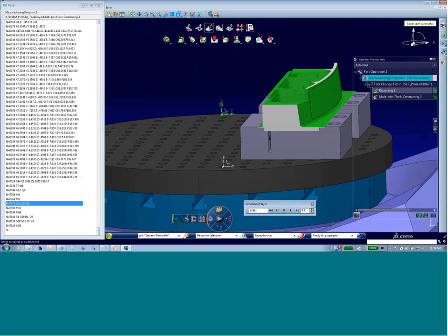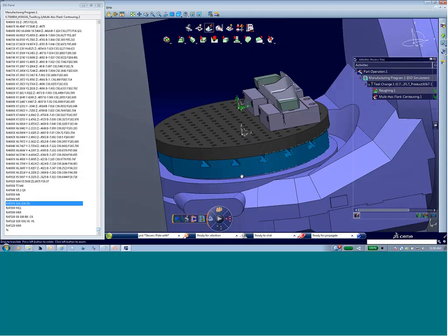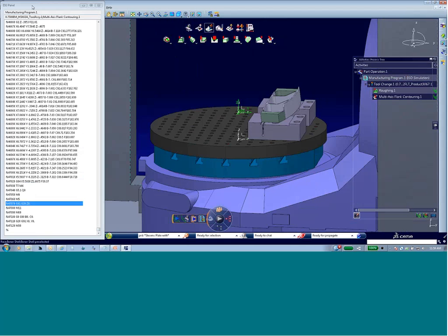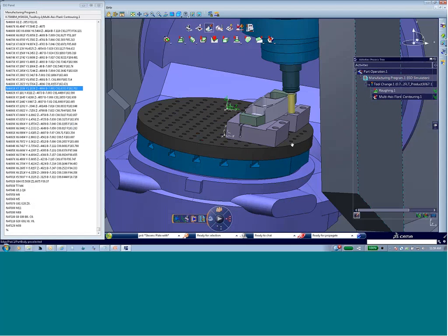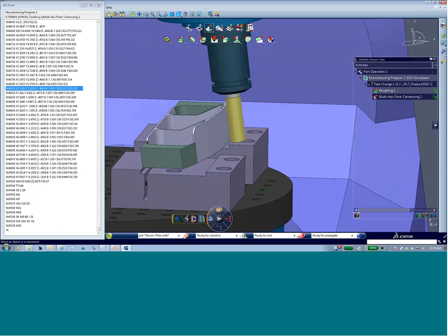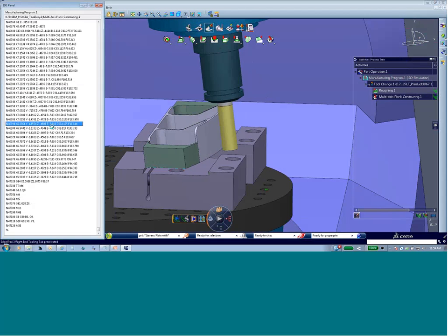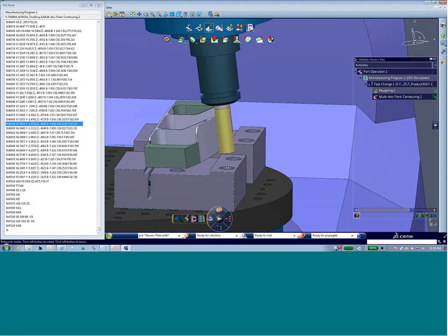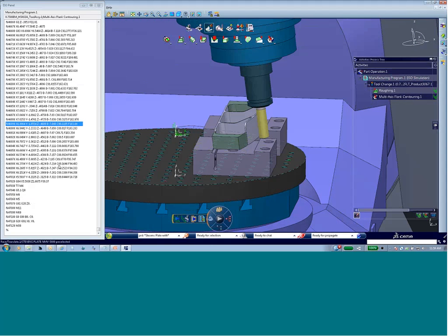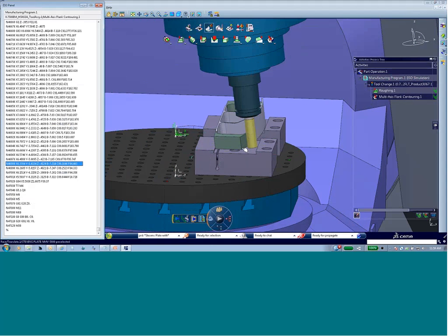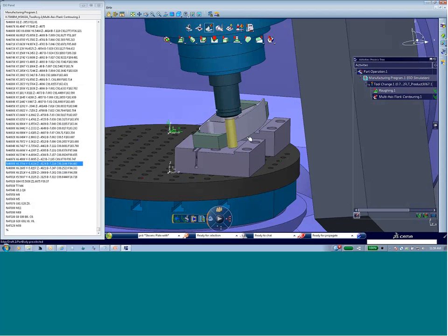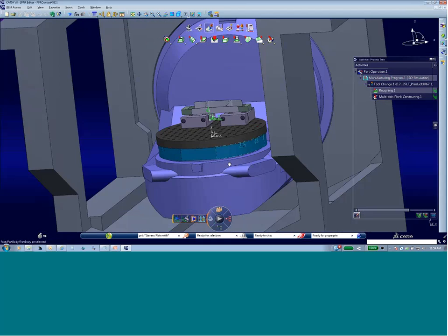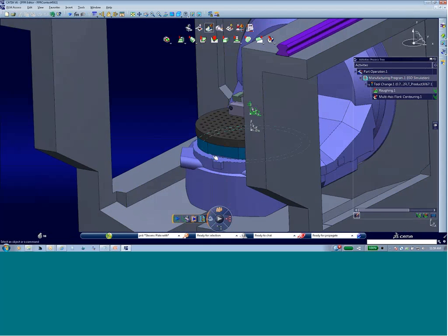Okay, so I can close the simulation. Even after I close the simulation, the ISO toolpath panel stays active on the screen, and any toolpath that I highlight with the cursor, it will put the tool at that position in the toolpath. So if you want to do any static checks of cutter locations, you could go back through the program that way without going back into simulation.